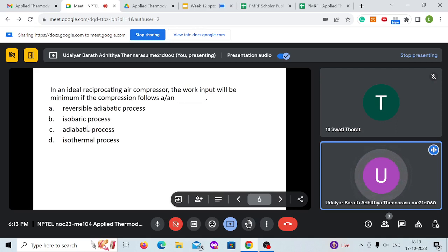In isobaric compression the pressure remains the same, so it doesn't make sense. Even then, the work would be P into delta V, which would be a larger work done. If you draw all the processes on a PV diagram, the process which has the least area under its curve will have the least work. In that sense, the isothermal process will have the minimum work under the curve.